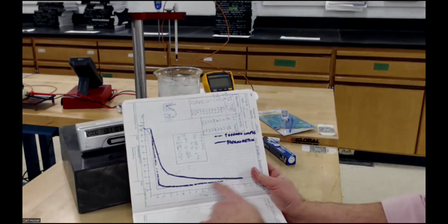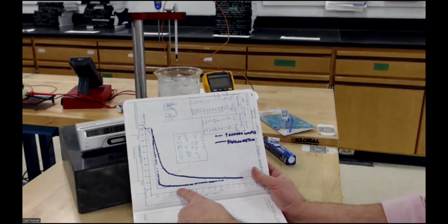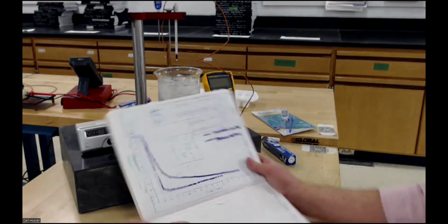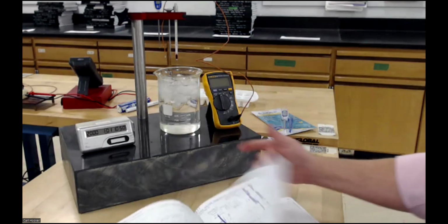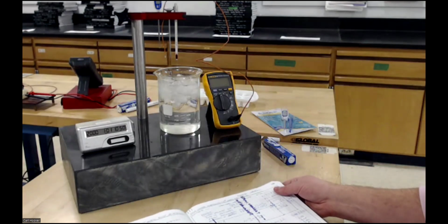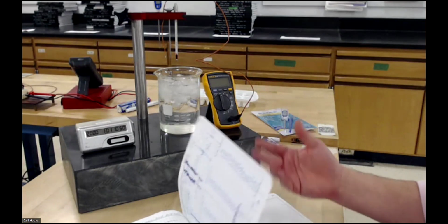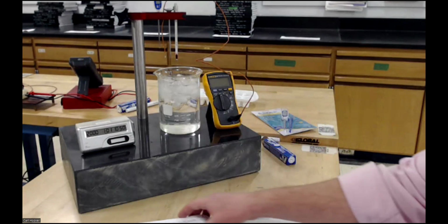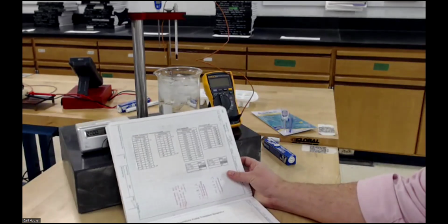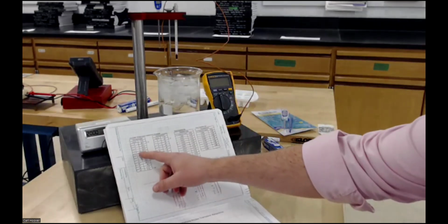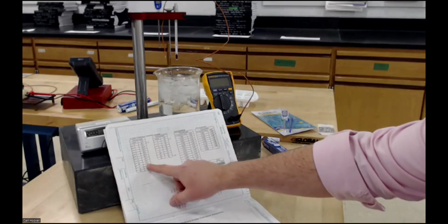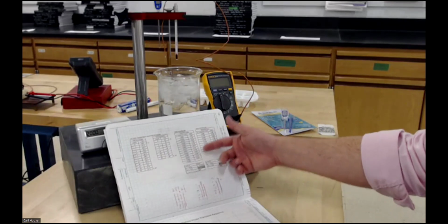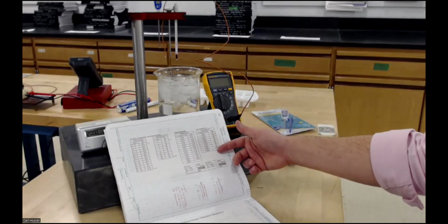As far as your data, you can expect to have, I've drawn it in kind of purple here, a couple different sensors, temperature over time. You'll end up tabulating that data as you go, computing error fraction, and you can do some of the analysis in Excel if you'd like. So you can get time and temperature for the thermocouple, time and temperature for the thermometer, for example, error fraction, and continue on out.